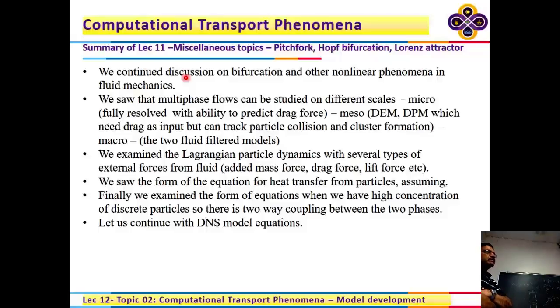I was thinking that maybe if I change the viscosity, I might see some variation. Yeah. When we understand how these equations are solved, there is in the CFD algorithm a unique problem called the pressure velocity coupling, and we will look at that after we see in general how we solve differential equations by discretization. Finally we will arrive at this pressure velocity coupling, which is unique for the incompressible Navier-Stokes equation. The problem that we are seeing in COMSOL may come from the way they are handling this coupling.